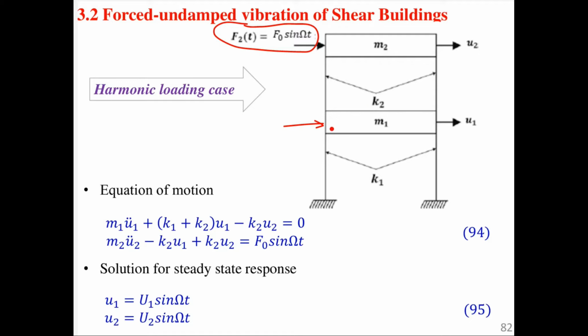at the floor levels. So we expect some effect, for example, because of the axial load, we expect some buckling of the column. If they are long columns, slender columns, we expect some buckling. But again, we are ignoring that because we are only concerned about the lateral force. So you can see there is a lot of simplification.